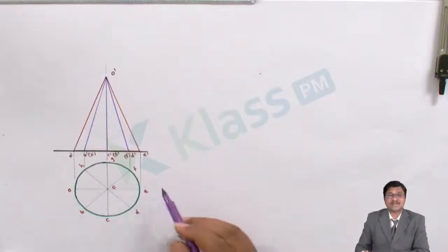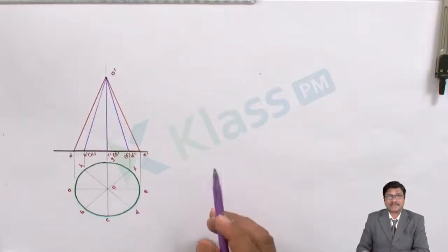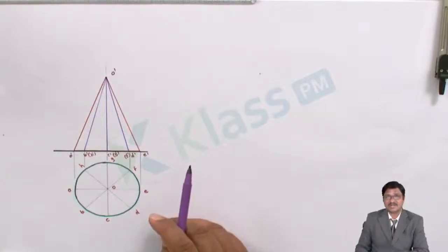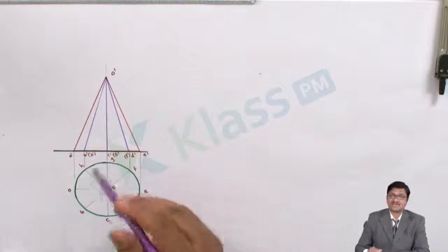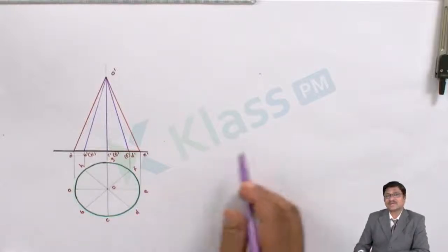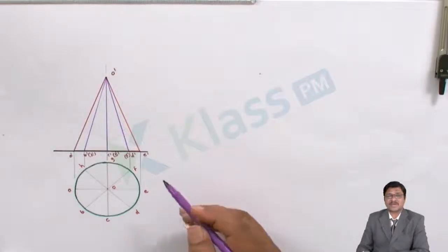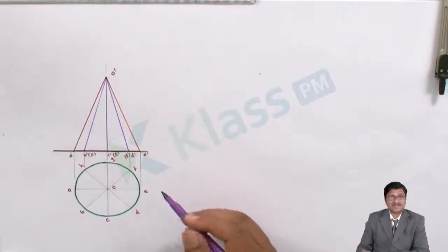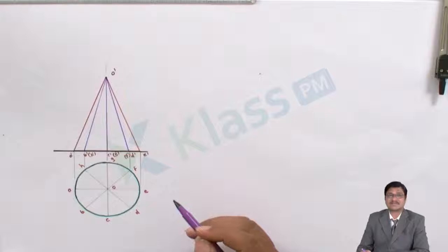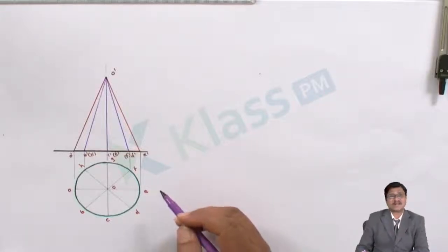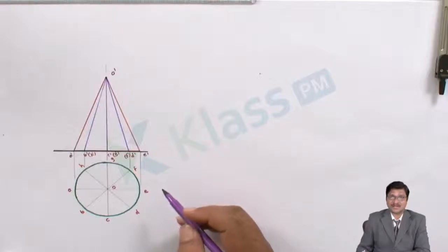So now let me consider how it will be done. As I explained, it is a part of the development of the surface. Before adding the journey of the ant, let us develop the surface, considering the cone itself. Whenever a cone is given, you have to apply the radial line method. For that you have to consider some calculation, which is nothing but the sector angle formed by the developed surface.